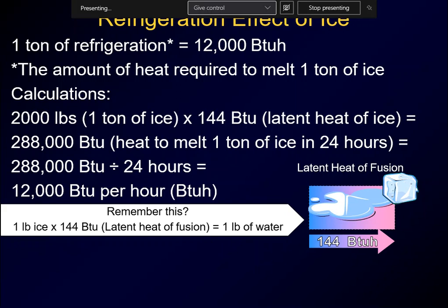So, for example, you may have a system that's a GSZ 36, whatever, AX, some random model number, but the number that I'm looking for when it comes to sizing is that 36. Well, what does 36 tell me? 36 tells me it is 36,000 BTUs. 36,000 divided by 12,000 is 3. That's a 3-ton system. And it could be half of 12, so it can be 18.